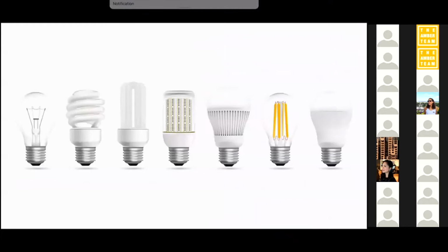And the answer is different depending on what type of lamp you have. The way an incandescent lamp works is we have the power, the hot, going in, and then the power goes across this little filament, which is wired up, curly like that, and then it comes back through the neutral.